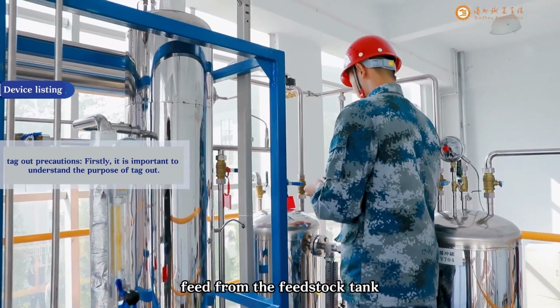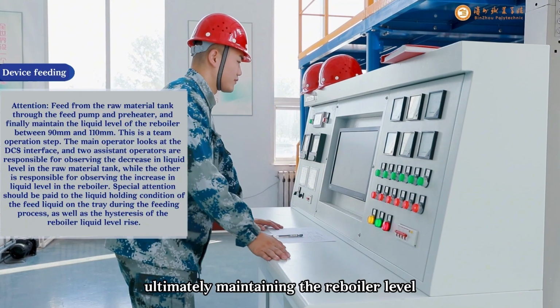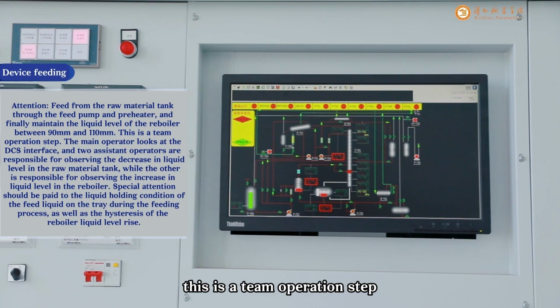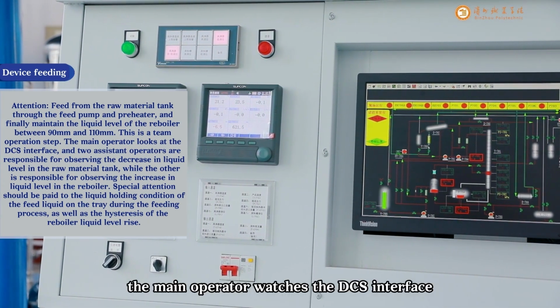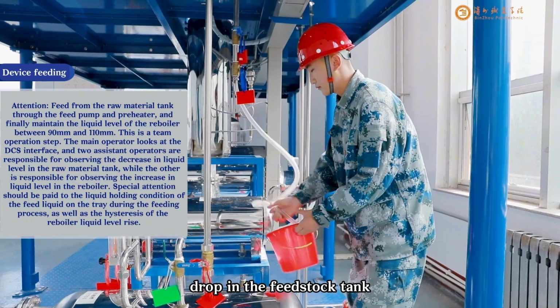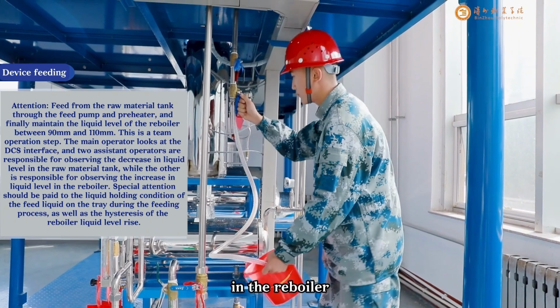Precautions for this part: feed from the feedstock tank goes through the feed pump and preheater, ultimately maintaining the reboiler level between 90 to 110 millimeters. This is a team operation step. The main operator watches the DCS interface. 2 assistant operators. 1 is responsible for observing the level drop in the feedstock tank. The other is responsible for observing the level rise in the reboiler.